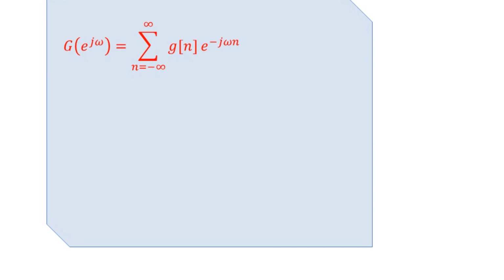In order to evaluate this particular methodology, whether there are any limitations or not, here we are trying to analyze the effects of windowing first of all before application of the forward Fourier transformation, and the evaluation of the frequency samples of the Fourier transform via the discrete Fourier transform, that is DFT methodology. So before making interpretation of the spectral contents of the signal, first of all let us examine the relations between the transforms and corresponding frequencies.